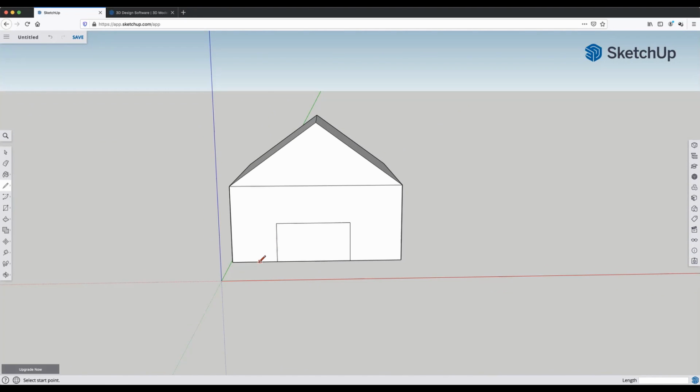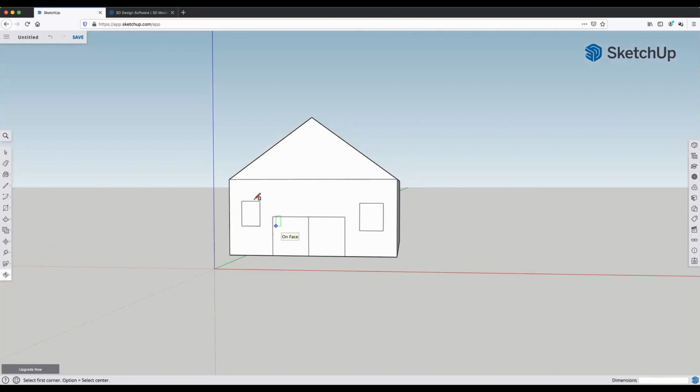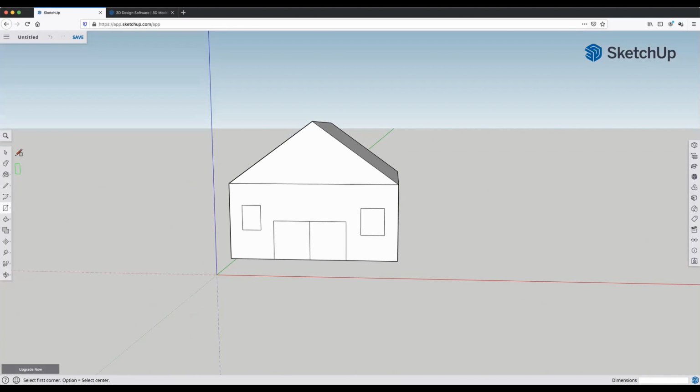As you can see, when I was drawing that line, if you check the lower right-hand corner, it'll tell you the height. That's always good to follow your measurements on your objects. If I wanted to, I can draw another line to put down the center of this, or you can just use the rectangle tool and draw a door that way, or a frame, to be a little bit more precise. There we go.